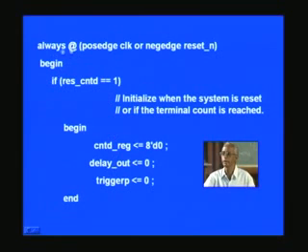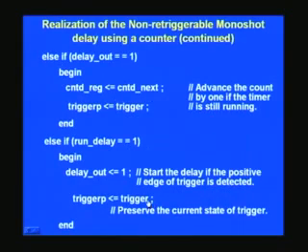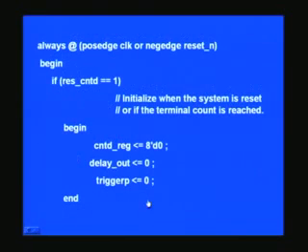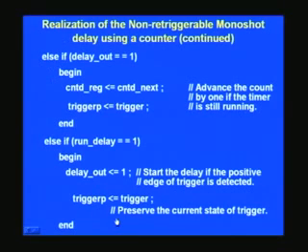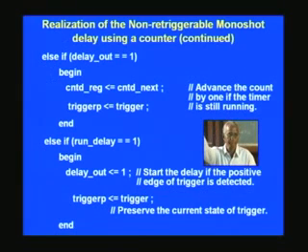It goes out of the always block, right? No other statements occurring later on will be entertained. Similarly, if this is not satisfied, only then will it go to the next one. And if that is satisfied, it will execute it and once again come out of the always block. And so is the case for every other thing.